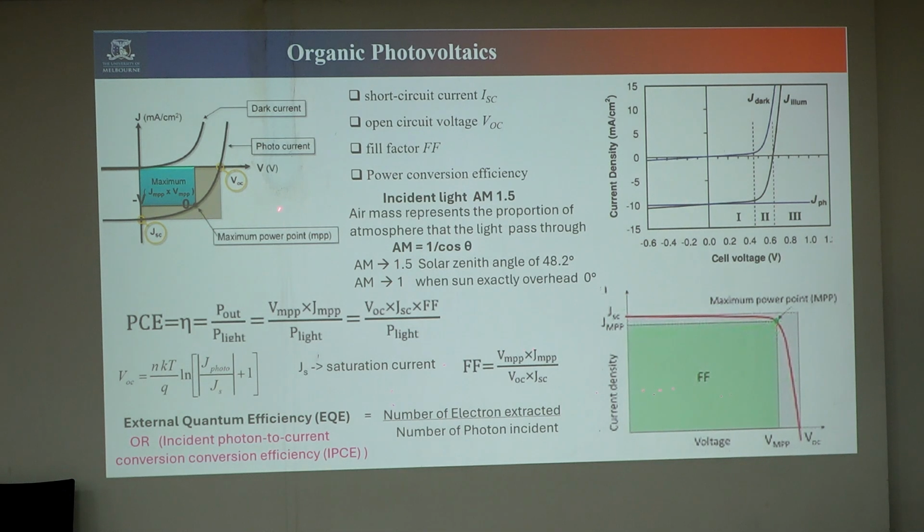In this IV curve, we multiply the x and y axis, current into voltage, to get the power. Where we get the maximum power, somewhere here, that is the maximum power point. That is why we draw the squares. If we divide the inner square by the outer square, the ratio is called the fill factor, because the inner square completely shows the squareness. That's called your fill factor.